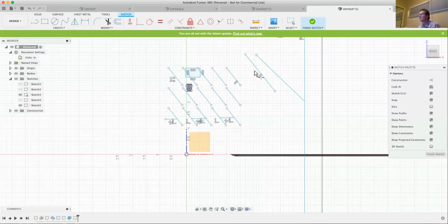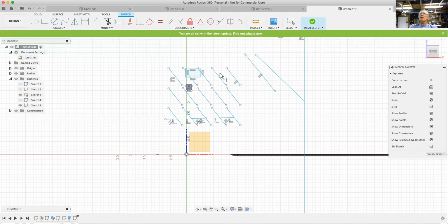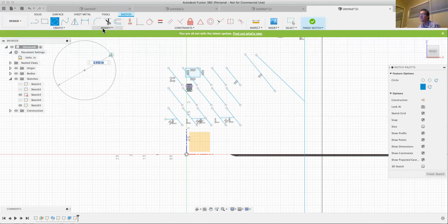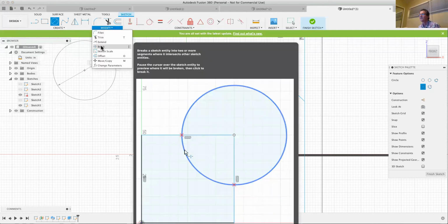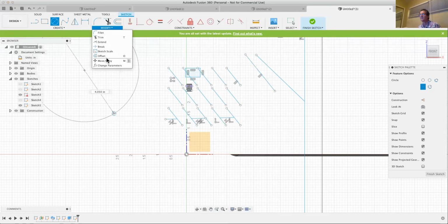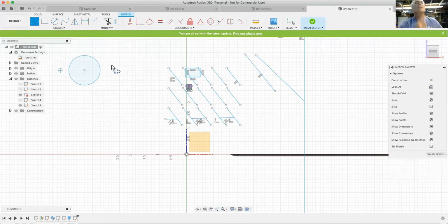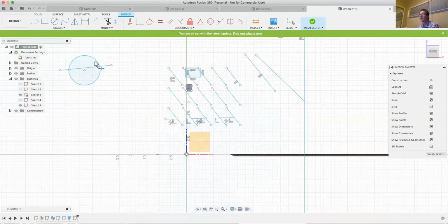Break kind of allows you to break something into two elements. But is it only when it is already, say, a square with 4 corners and you're breaking an existing junction between 2 line segments? I believe, let's see here, modify, where it intersects other sketch entities. Okay, so let's do a circle there, and let's do a line through it. And now let's modify break right here. Got it. So this time it broke this guy.